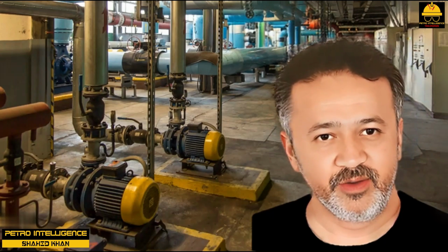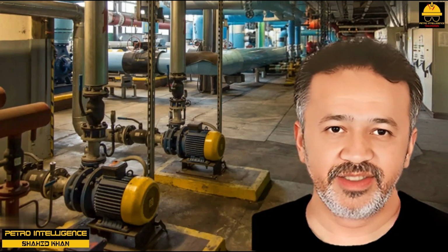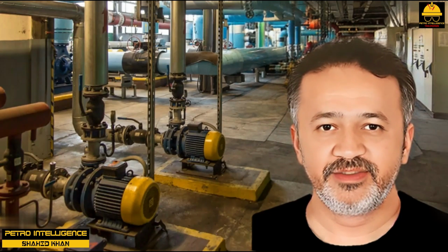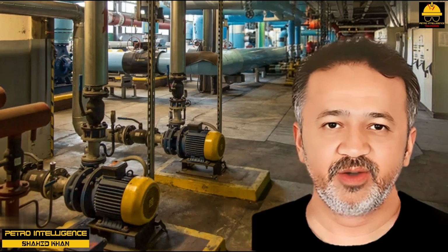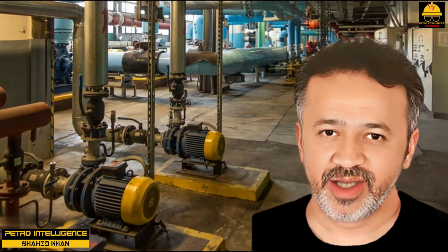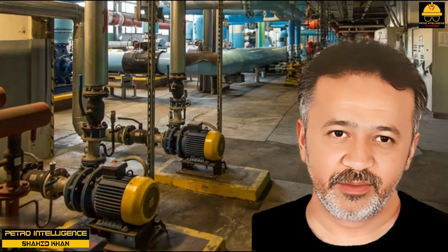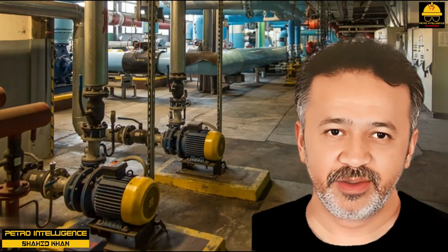It is quite important not to operate a turbine-driven pump by manually throttling the steam flow to the turbine. Let's assume that the operators have set the turbine speed at 3,500 RPM by adjusting the steam inlet gate valve upstream of a malfunctioning governor. Suddenly, the discharge flow control valve cuts back, and the pump's flow decreases from 2,000 to 1,200 GPM. The pump speed will then increase, because fewer pounds of liquid are being pumped and less horsepower is required to spin the pump. The pump speed rises to 3,800 RPM.